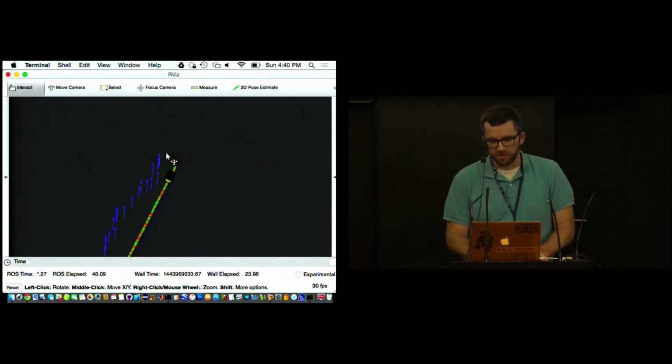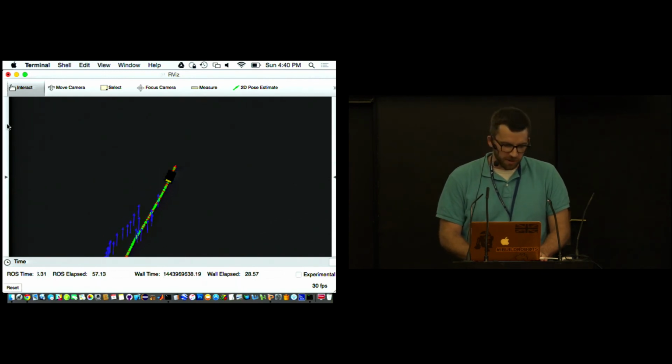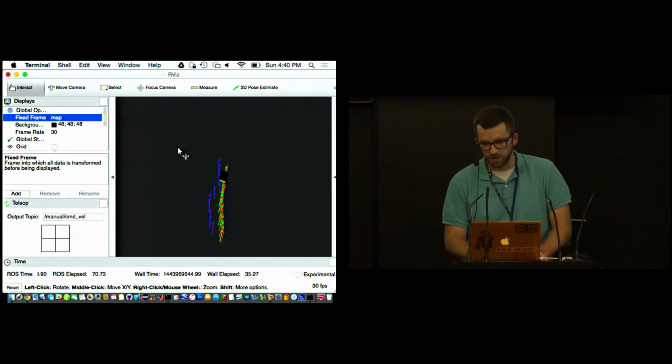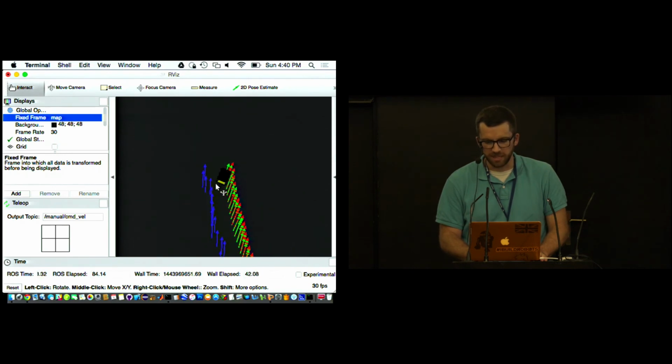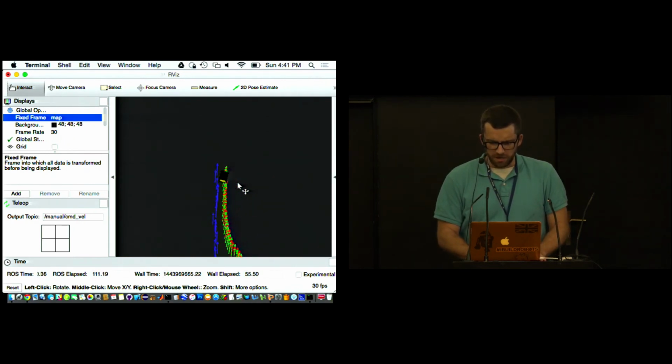And this blue thing here, this is the output of navsat_transform_node. So that's getting fused with one of the state estimates. And so I can show you, and I can explain this too when you start seeing how it looks a little off. This is when you're looking at the output of the map frame version, right? So every time you get a GPS measurement, you see the robot kind of jump a little bit. And you can see the difference between the way the robot thinks it's headed and the way it appears to be headed according to these GPS points. So that, again, is a result of this IMU not being quite right.